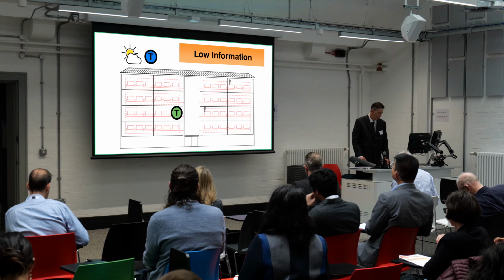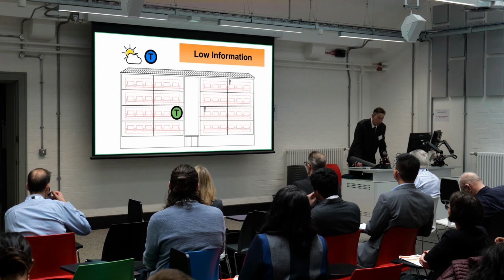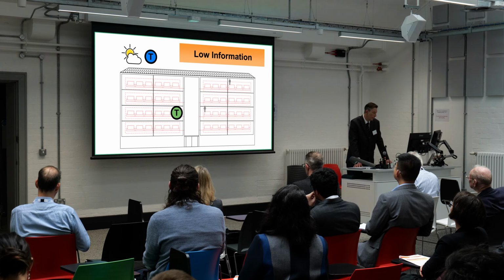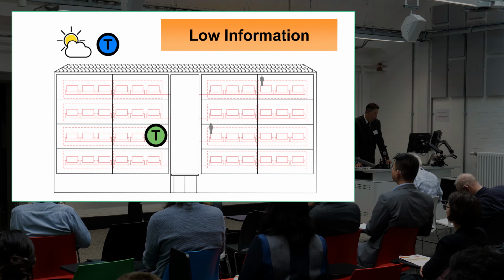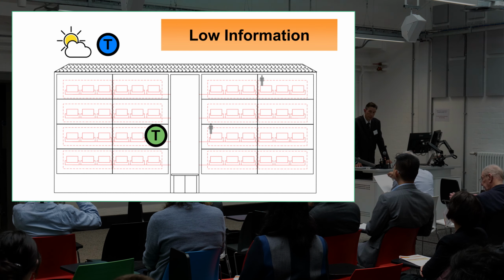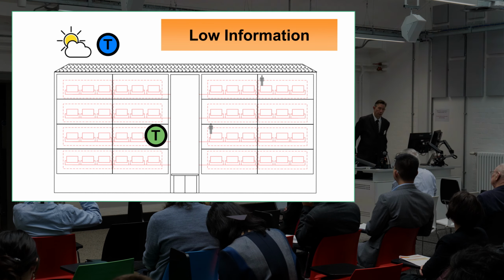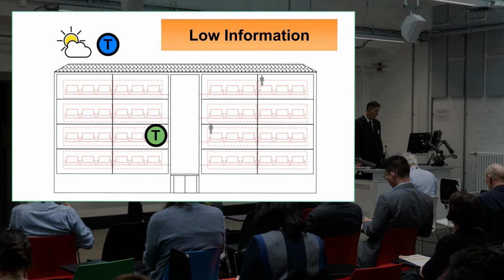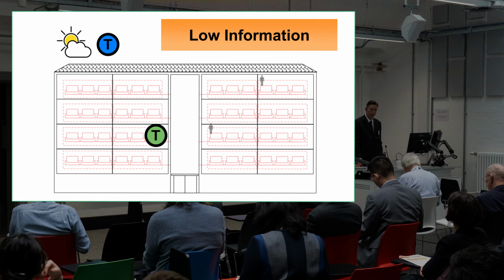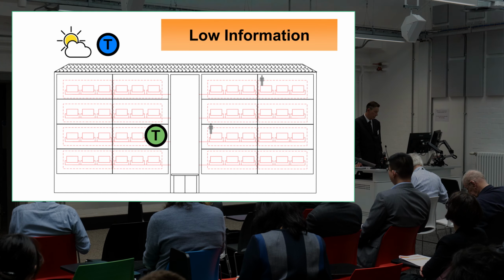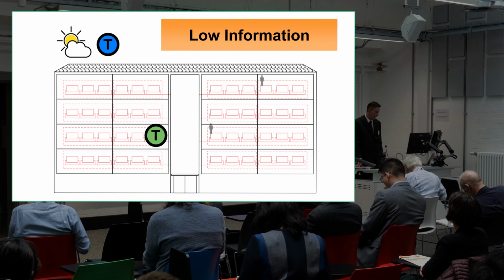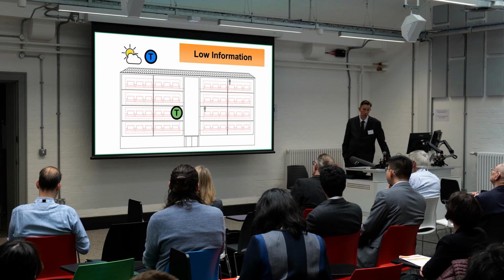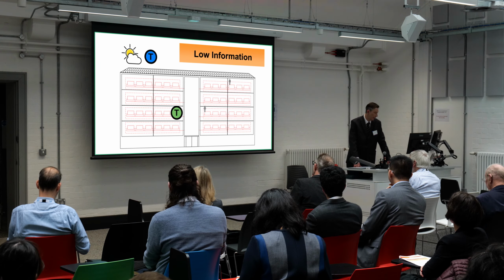So to begin with, we're going to look at a typical low information building. We have a building here with a wet heating system with radiators with mechanical TRVs attached to them. Somewhere there's a plant room with a primary heat source and heat distribution plant, and a building management system with sensors and actuators to control the plant. But outside of that, it's very common for there to be very little information about the actual spaces we're conditioning, which is being fed to the BMS.